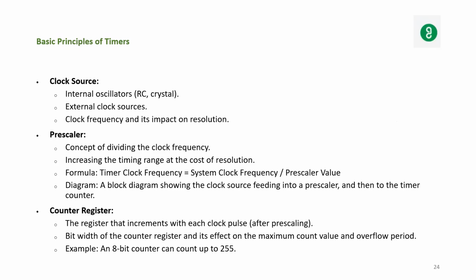For timers, the basic thing is that you have to generate the clock. The clock may be internal or external. You can use internal oscillators, RC or crystal oscillator, or externally you can use clock sources. Clock frequency has an impact on resolution.